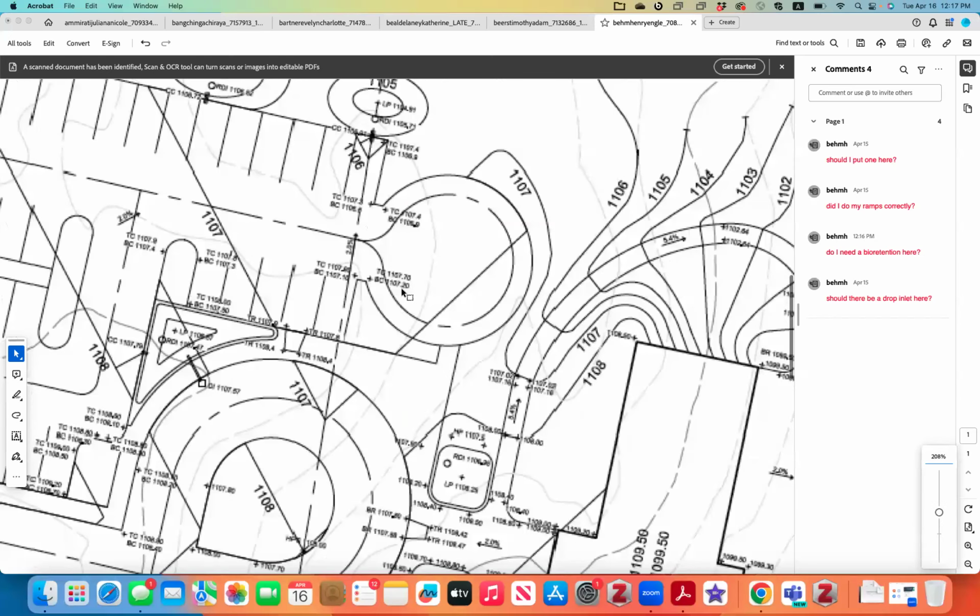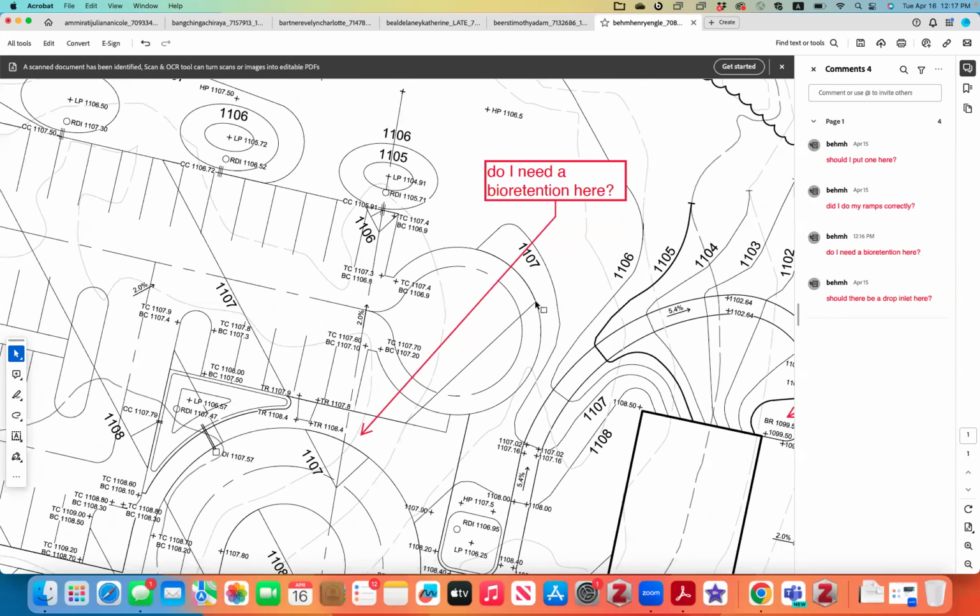Right. The key thing is you need to know if you would have standing water by moving this line to here. So whenever this line intersects with your curb, I would know, okay, this is the lowest point. Once we have the lowest point, I know if I don't have a curb cut here, water will pond here.